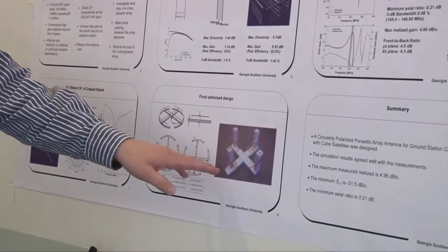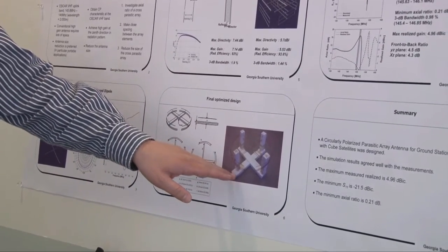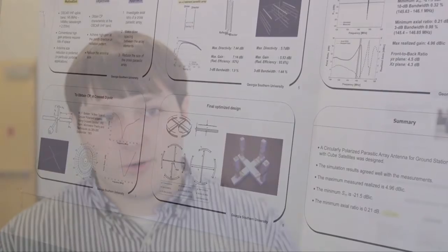A lot of the satellites do employ different bands for communication. So if I could manage to put multiple bands in one antenna, that would also be highly desirable. Another thing would be to increase the gain of the antenna. This particular antenna has a 2-element design, so the next step would be to add what is called a director to the bottom of this to try to get a little bit more forward gain and performance out of the antenna system.